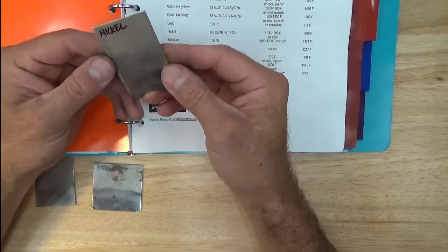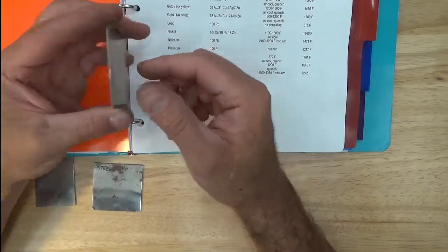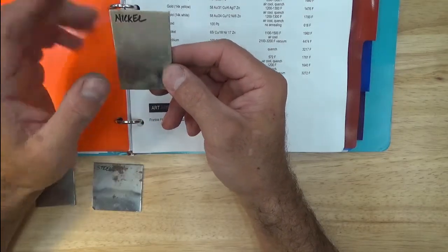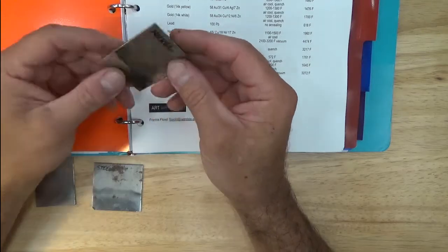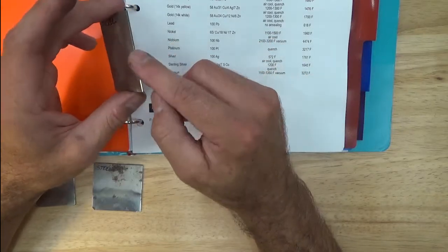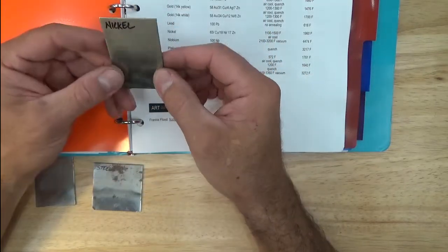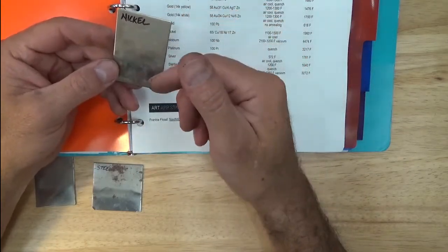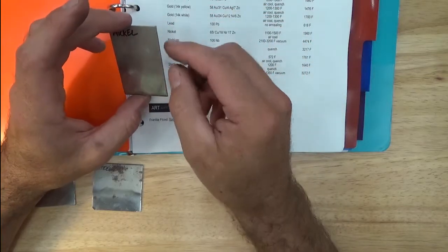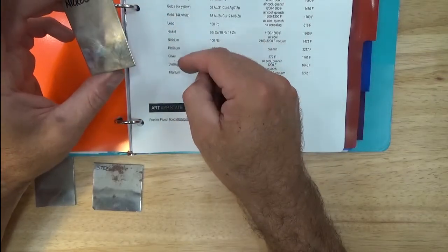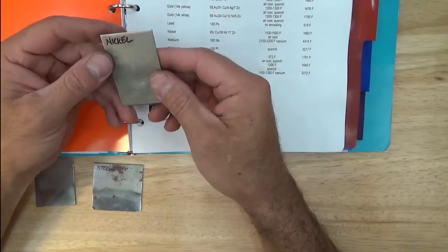And man, I had to just wail on the piece to get it to move at all. So it's not even close to copper in terms of being able to form it, but it is beautiful to silver solder with, because your silver solder seams typically blend a little bit. There's just a slight color differentiation between them, but a lot of students like working with a white metal for various reasons, and if that's the case, they might gravitate towards nickel because it's more affordable than silver or sterling silver, but yet you still get that white surface.